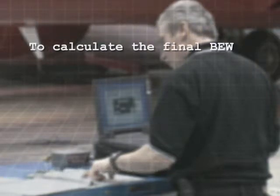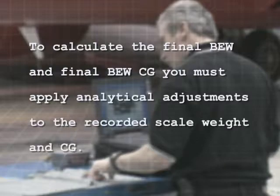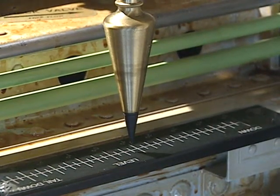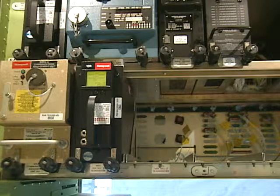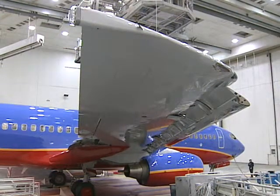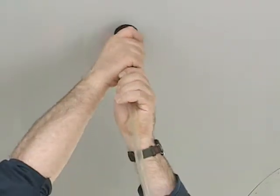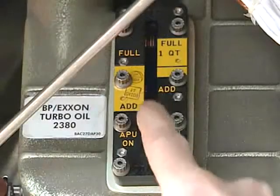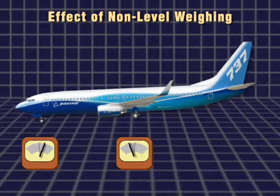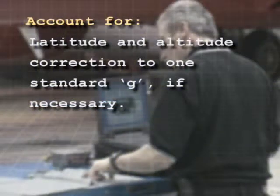To calculate the final BEW and BEW CG, you will need to apply analytical adjustments to the recorded scale weight and CG to account for the effects of removing items that were on the airplane during the weighing but are not included in the BEW, adding items that were not on the airplane during the weighing but are included in the BEW, full extension or retraction of the flaps and slats to their BEW defined positions if these positions are different from what was weighed, adding drainable fuel that is to be included in the BEW, adding any system fluids that were not at their full dispatch-ready levels during the weighing, non-level weighing if the airplane could not be leveled to a zero-pitch attitude, latitude and altitude correction to 1 standard G if necessary.